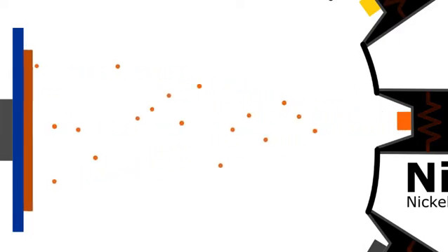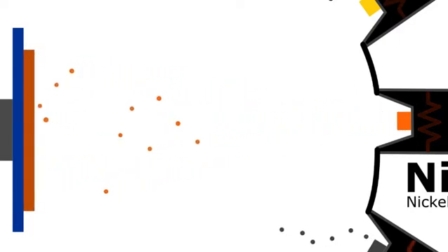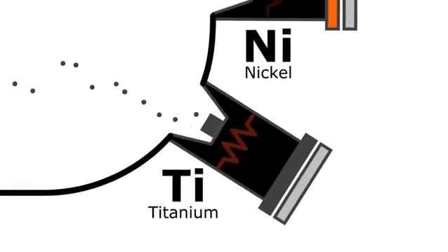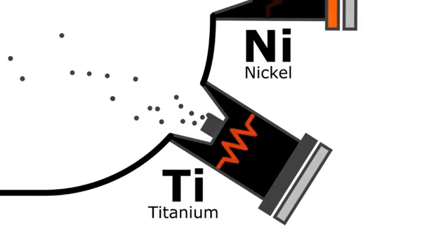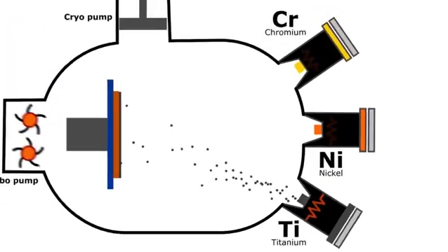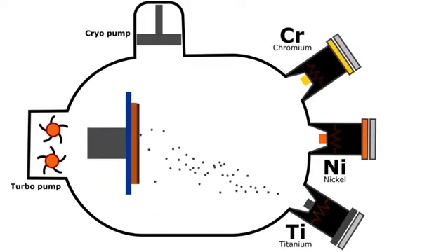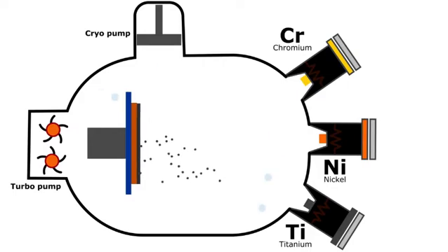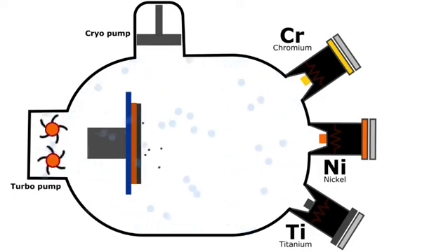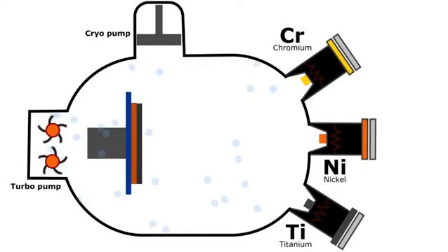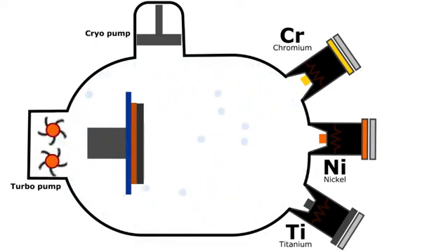Using this method, a really thin film can be achieved because the molecules come out of the evaporator in a beam, and the rate at which the molecules are emitted from the cell can be controlled precisely by controlling its temperature. The most important thing of this technique is the setup, which must be in an ultra-high vacuum environment. This is to minimize impurities and also minimize the collision between molecules along the way to reach the substrate surface.